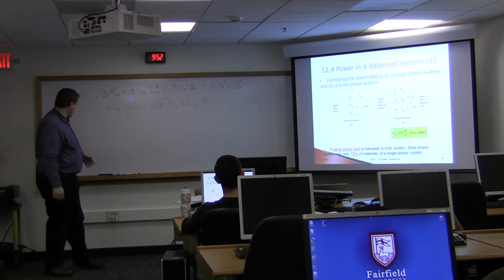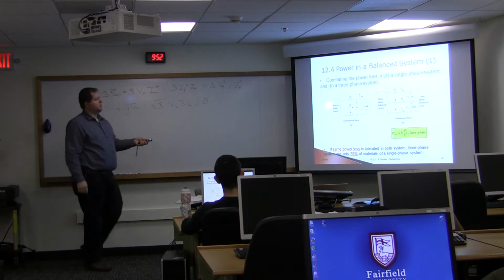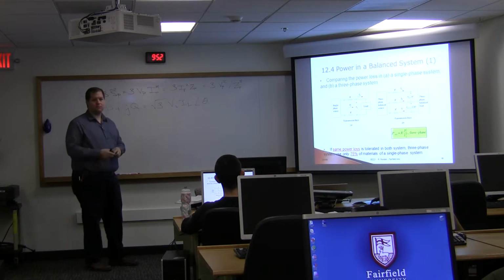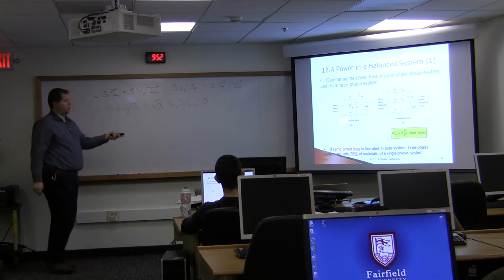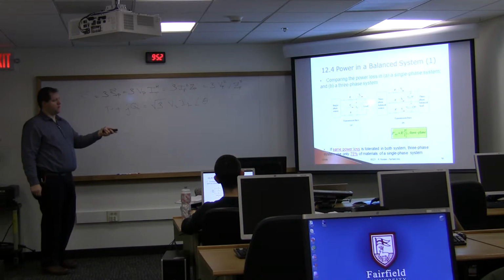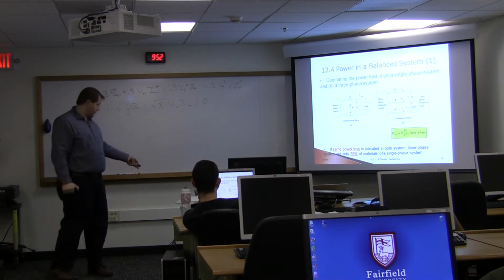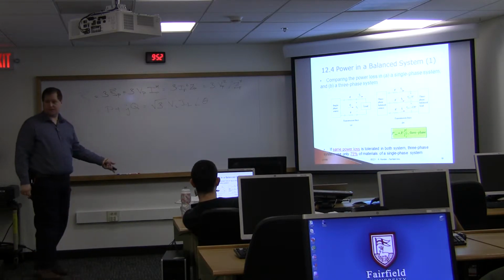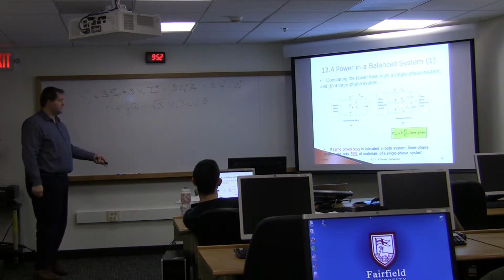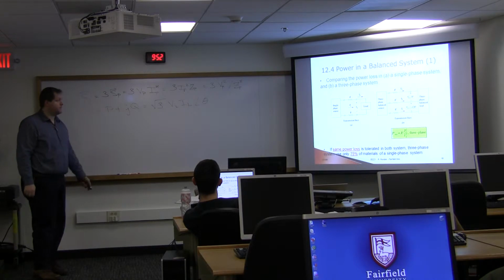So if we were looking at a single-phase system, right, it uses 2 wires. Current flows in from the source to our load, and back out through the neutral line. This is like what we have in our house, one of these wall sockets. Even though there's a third wire, these are not 3-phase systems, right? These are all single-phase. The third pin is just a ground.